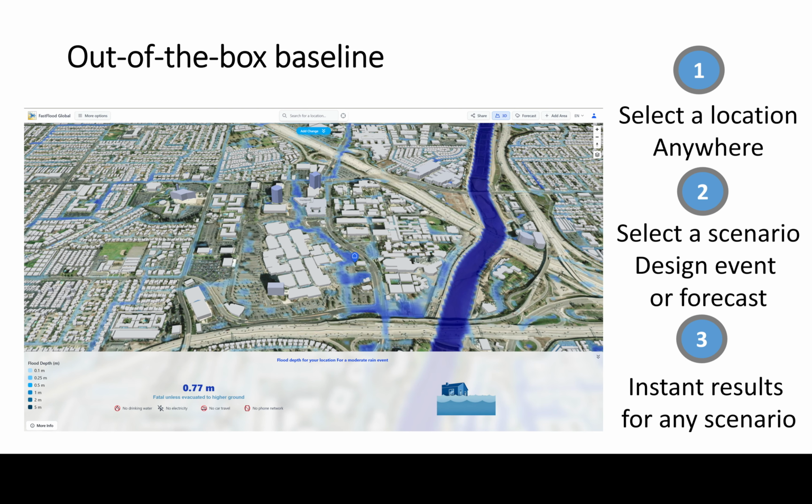And here we often talk about probabilities. So we talk about the yearly probability of occurrence, and often that's phrased as a return period. So a 100-year return period event is quite an extreme flood that would happen once every 100 years on average. Now, it doesn't guarantee that in the coming 100 years such an event is going to happen. It's just a probability. So it's like tossing a coin and saying, look, we have a 50% chance that we're going to see heads. But in reality, you could throw heads 4 times in a row. Although exceedingly unlikely, it can happen, right? It's probabilities, it's not guarantees.